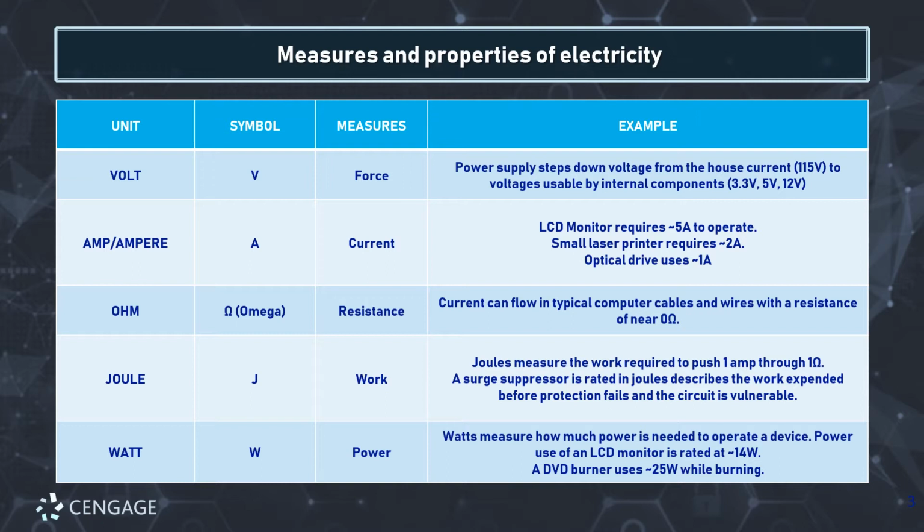Think of it as a joule rating, let's say 500 joules, as being the top of the hill. And you have a spike that hits at 300 joules. Well, boop, it goes up to that mark, but it does not tip over. It just sits there. And then it can be ratcheted back down. Or you have one that's 400. Well, that's still within the protection range, so that spikes up, and then it walks its way back down.